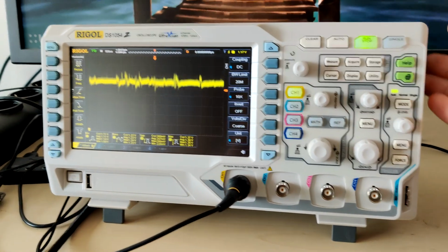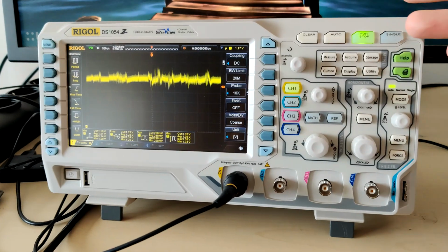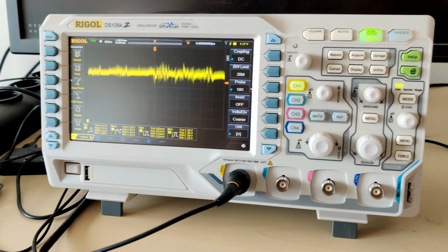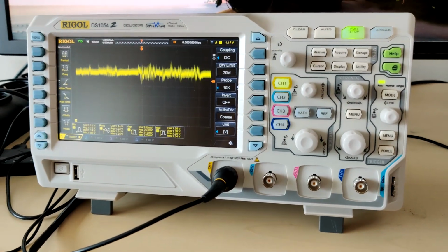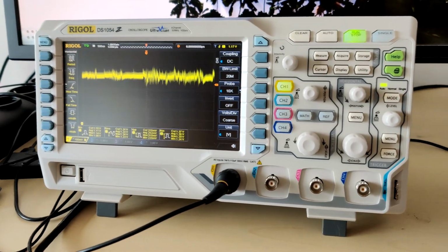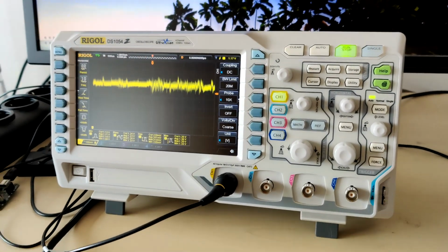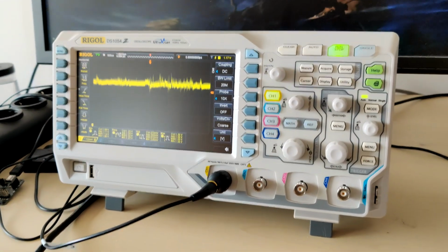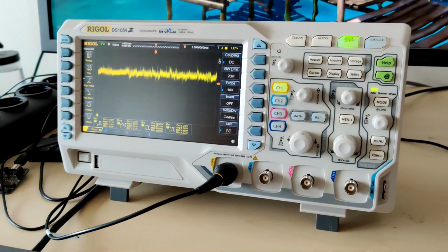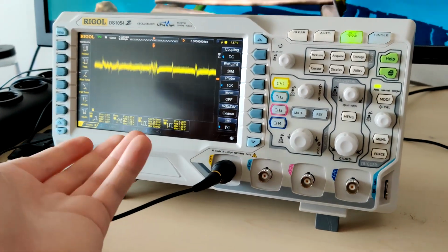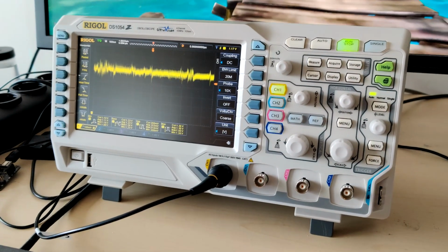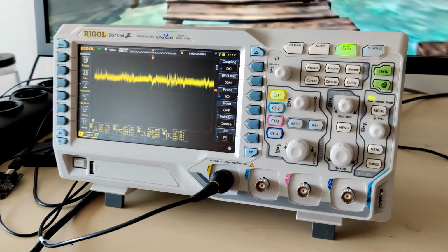And yeah, primarily I'm going to use it for just showing what certain mods do to cards, how good cards are compared to one another. Like, Cheap-ass Chips is going to start soon with the HD 58, was it? No, 6850. I will compete in that. These cards seem fairly cheap. I'm probably gonna get one or two, and I do plan to e-power one of them. And having this oscilloscope now is a perfect opportunity for that, because I can test the quality of voltage regulation before I e-power it, because those cards have fairly pathetic 3 or 4 phase VRMs.